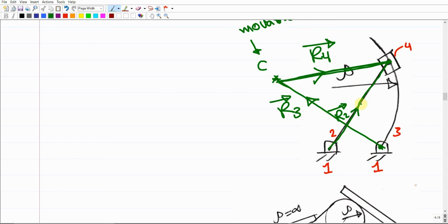You should understand that this is R2, then we do have R3, we do have R4. So the loop is still open. If we try to move R2, R4, R3, the loop is still open. To close the loop, we have to close it with this position vector as the R1 vector. So you're going to work as if you are already moving in this direction: R1, then R3, then R4, then R2. Right? This is the loop. It has 4 position vectors. Make sense? You should understand that R3 works for the length number 3.